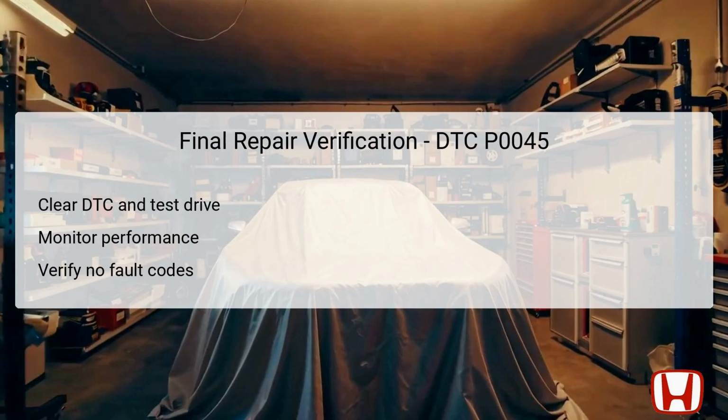Once all necessary repairs and replacements have been completed, it is crucial to clear the DTC from the PCM to reset the system. After clearing the codes, a test drive should be conducted to observe if the changes made restore proper engine performance and resolve any existing symptoms.